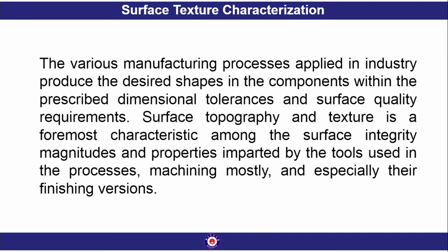The various manufacturing processes applied in industry produce the desired shape of the components within the prescribed dimensional tolerance and surface quality requirements. Surface topography and texture is a foremost characteristic among the surface integrity. Surface integrity magnitudes and properties are imparted by the tools used in the process, mostly machining and especially their finishing versions.